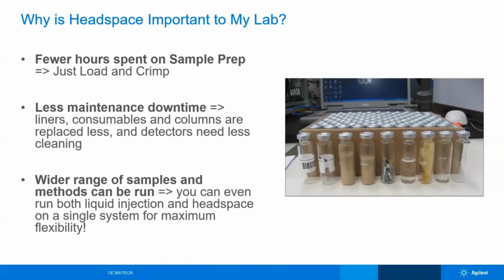Also, are there particular compounds or sample types that lead to a substantial amount of maintenance time? In some cases, you'll see extractions that are so dirty that the inlet needs to be switched out in less than a dozen injections. These sorts of analyses are perfect for Headspace. Everything that goes into the vial that's a solid, that's not volatile, stays in the vial. Additionally, you are generally going to have less wear and tear on your columns, fewer consumables switches, and your detectors, including your sources, generally need less cleaning.